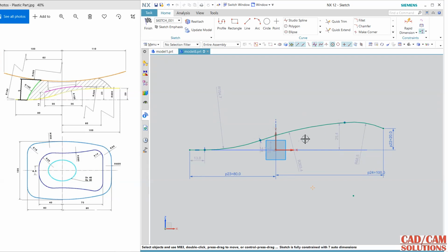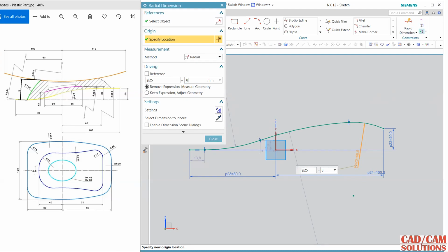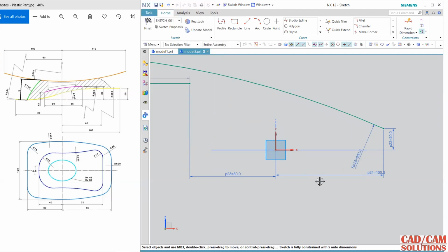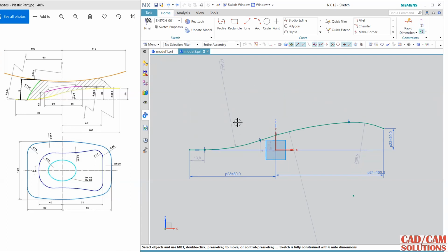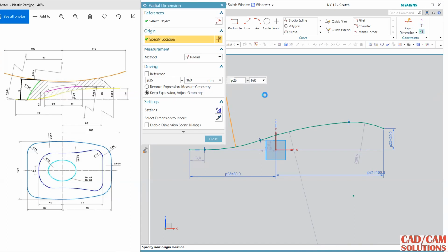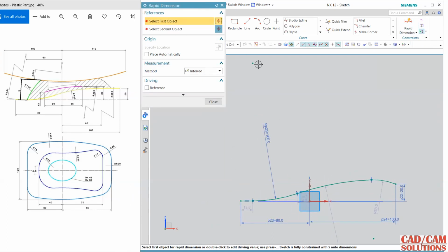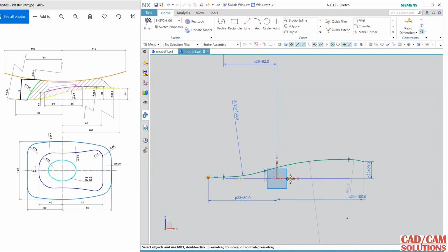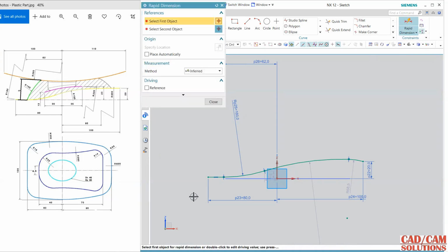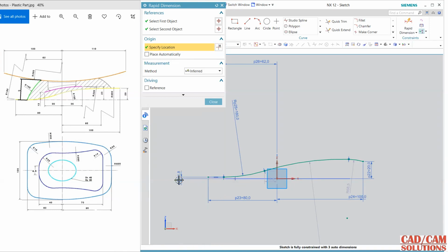Now I will try to create the same thing, tangent. Now it is okay, and the radius is 800. This is 800 radius. It is going so far, so undo it. First I'm starting from here. 160 is the radius, and the center point is 62 mm from the vertical. 62. Okay, and this point and this horizontal axis, this and this, click 0.